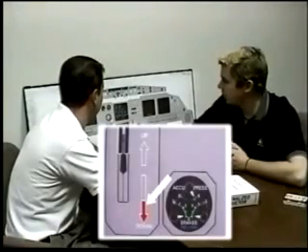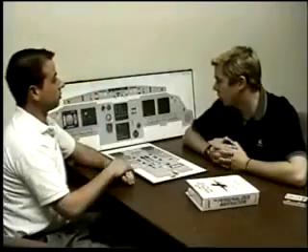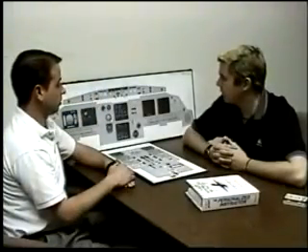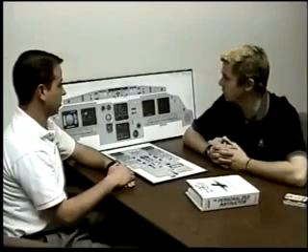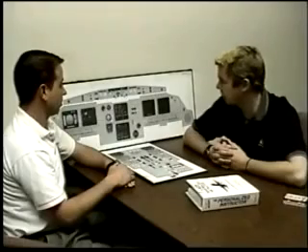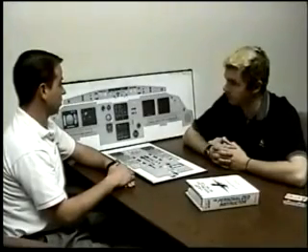This red down arrow on the landing gear panel, explain that to me. That indicates that the gear is not down, and it should be. It's accompanied by a warning horn, and it occurs 3 times. Below 750 feet, and the thrust is below 75% on one of 2 engines, or below 97% on 1 engine. Or if I'm below 750 feet, gear's not down, and the flaps are 3 or full.